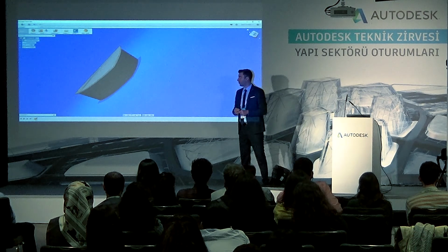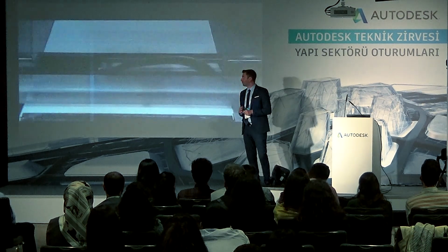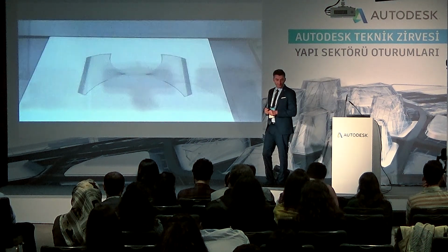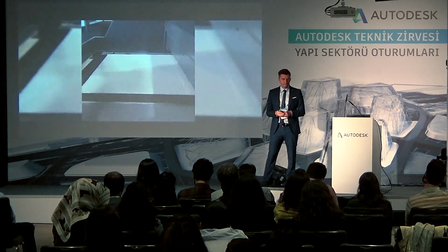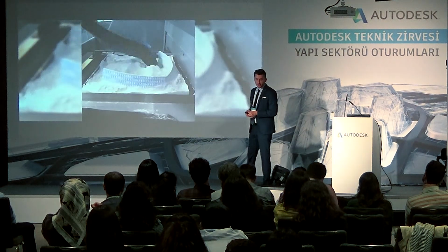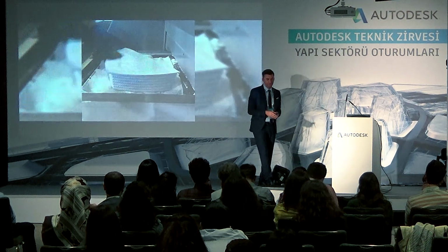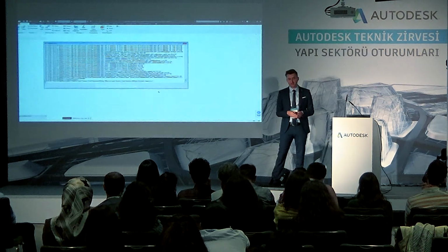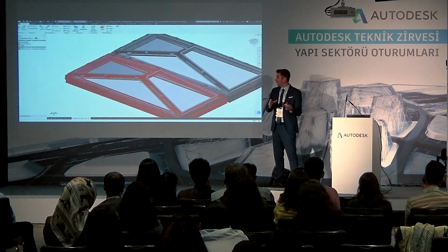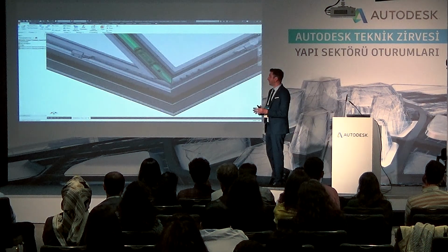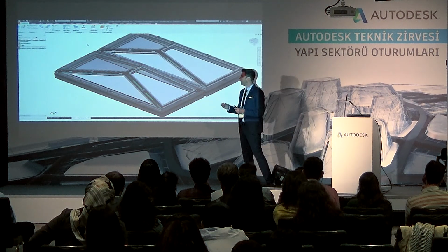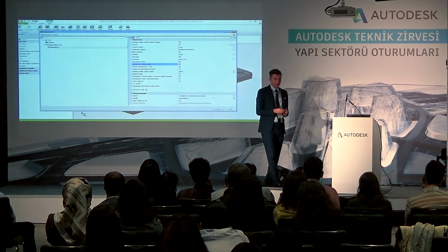This is where we prepare the model for fabrication, 3D printed the model, layer by layer, remove the excess material, and there we have the mock-up of the facade. And we are preparing for the last step, where we took the data from the design and we converted it into fabrication-ready information. We have the right tools that can generate all the bits and pieces that are necessary for fabrication.